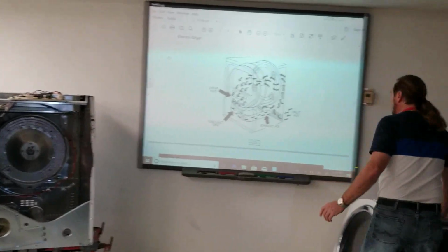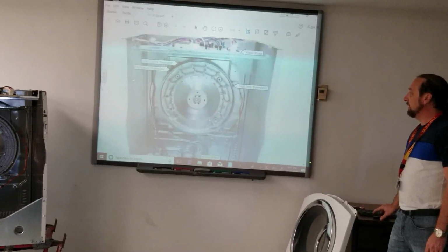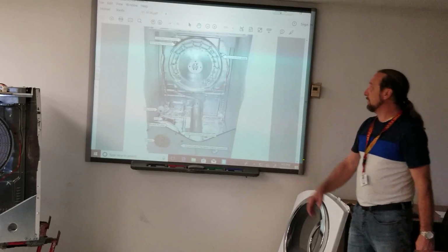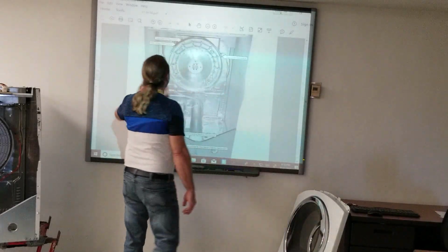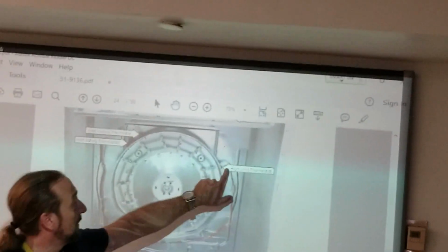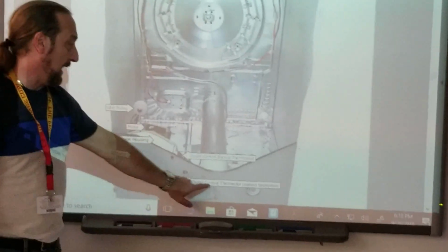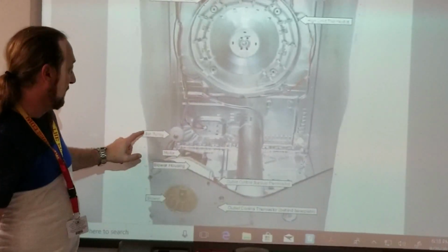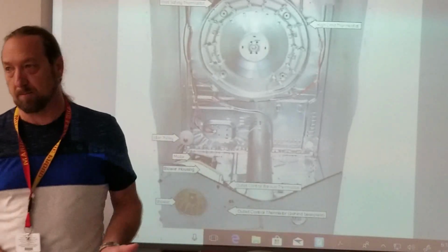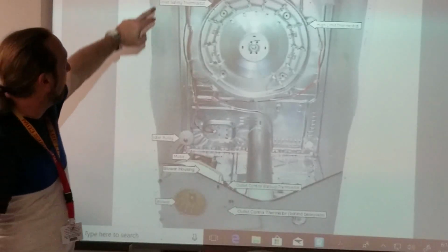You all have this book on your jump drive, and I'll upload it and attach it to the video. Here you can see the machine, basically the same machine we have there. We have the inlet control thermistor, inlet safety thermostat, high limit thermostat, outlet control thermostat, outlet control thermistor, your pulley, your motor, and your blower, and everything else. There's not a lot of things inside this drive. It's not filled with 1,000 parts in there. But let's take a look at a couple of things.